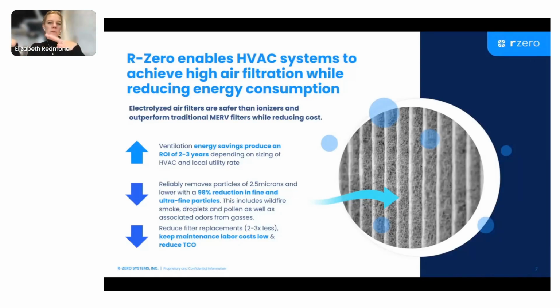Where we get into remediation, there are opportunities for looking at using advanced air filtration to remediate particular air quality issues. If you have a high level of particulate matter, we're measuring PM1, 2.5, 4, and 10. And across that whole spectrum, those have indications of different things.